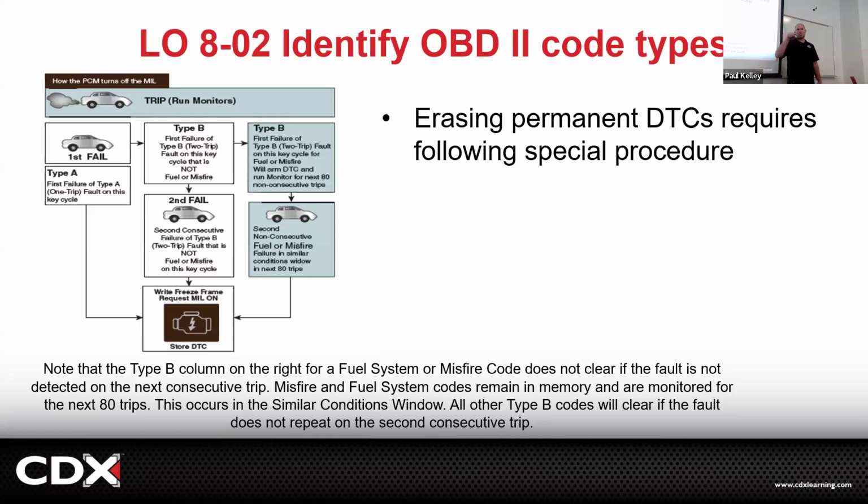So you guys know if you want to clear codes, you clear them. Technically, though, if you wanted, you could disconnect the battery and leave it disconnected for a while, and it'll probably clear it. But it'll also erase all your monitors, and they'll all go to incomplete. It's kind of similar to clearing codes. It also resets some other things, and so that's not the right way to do it.